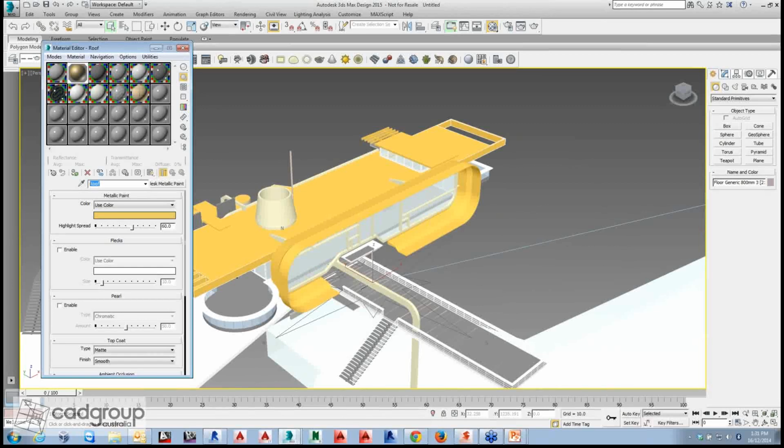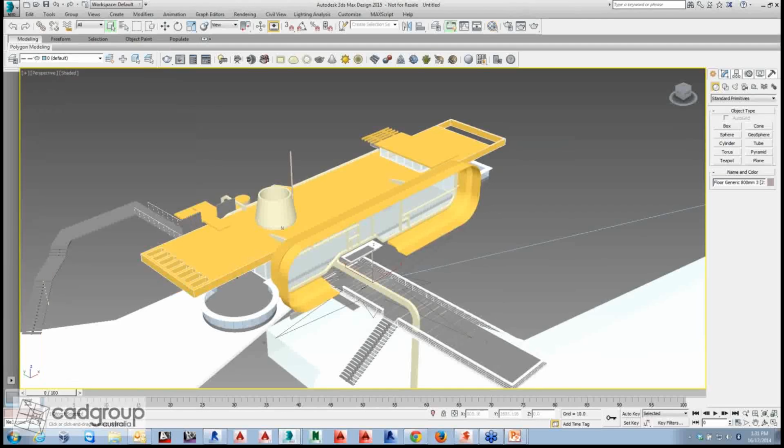And the advantage of using this suite workflow is it's a linked model. So if I have to make some changes, either I can do it within the 3ds Max environment or go back to the design software, which is Revit, change the models, and we can simply update inside 3ds Max using File Link Manager.